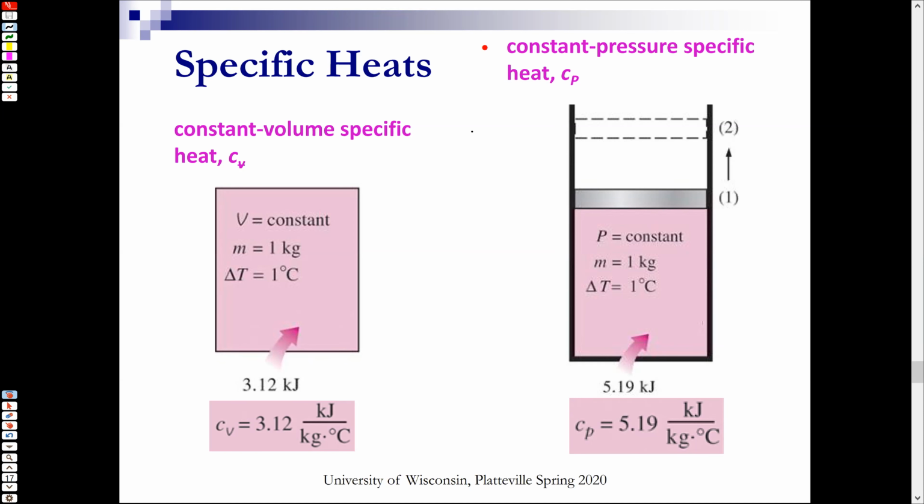Just keep in mind that Cp and Cv are also properties of pure substances. They change with temperature and pressure, like all other properties, but for most cases their change is not that much, so we can consider them close to average values. Specifically, for incompressible materials, Cp and Cv are always constant.